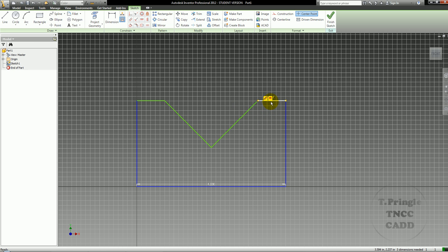Okay, I'm already in a command, so I need to right click on that and hit delete, and now these two segments are no longer equal. But for the purposes of this, I do want them to be equal. In a lot of cases what accidentally happens is we over constrain stuff that we didn't mean to, and then it's really difficult to get the rest of the information we need. Next I'm going to go ahead and finish dimensioning this piece. So this is going to be 3.5 and this will be 0.5. So now I can go ahead and finish my sketch